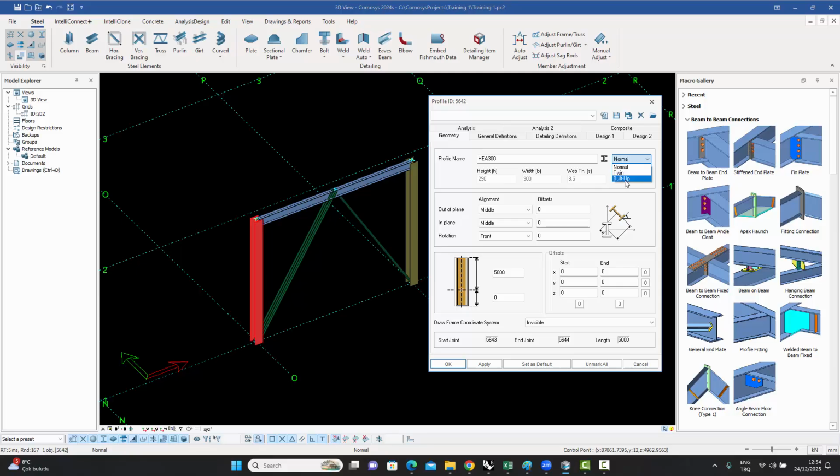And a built up section is very similar to a twin section as far as behavior is concerned, but it's different in the sense that twin profiles all need to be composed of the same section, whether they use it twice or four times or any other number of times. That is not the question. That is not the criteria. The criteria is that the same section needs to be repeated. With the built-up option, the sections can change as well.